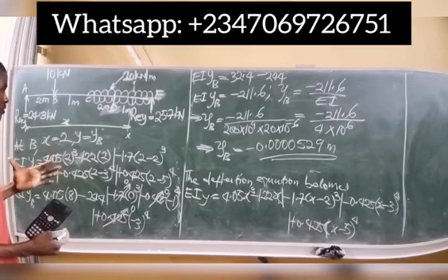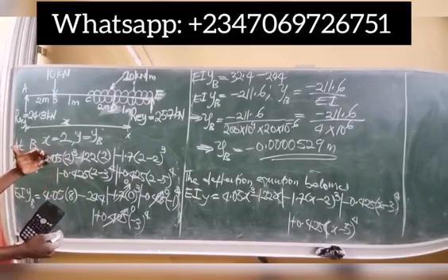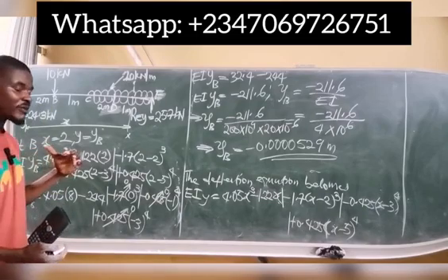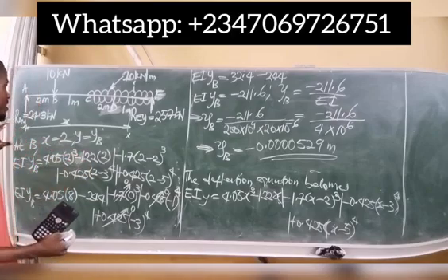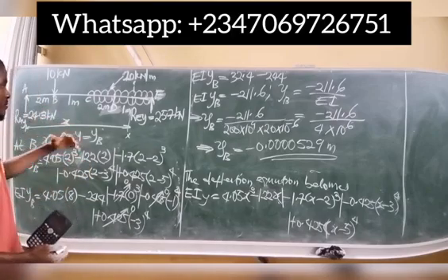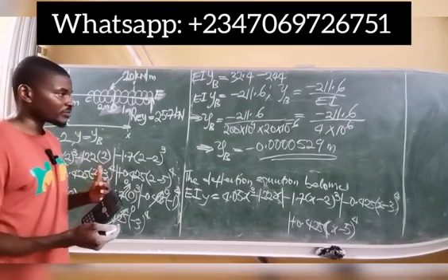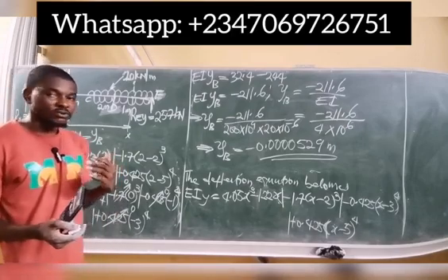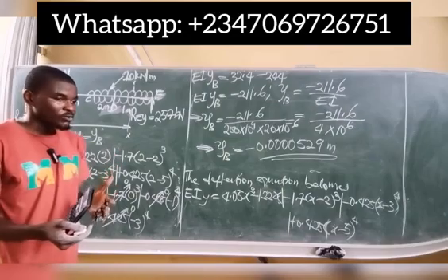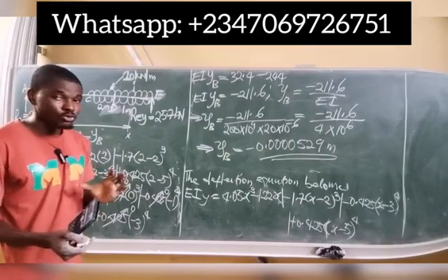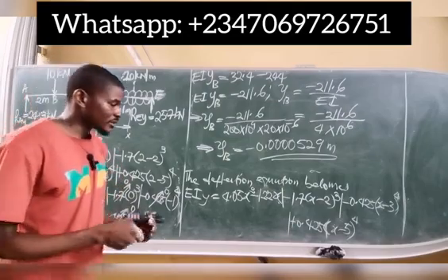Okay, you consider the intensity of the loads on top of the beam. So that's the method I'm going to use, simply by eye gauge. We have to weigh the weight on top of the beam and then check where the point that has the higher weight on the beam is. At that point, or very close to it, is where deflection is said to be maximum. I'm going to show you how to do that now so we can all see.